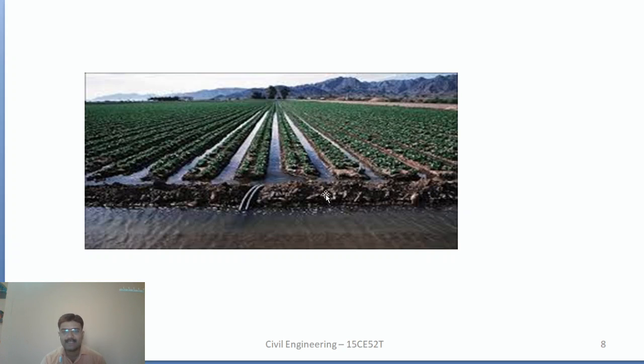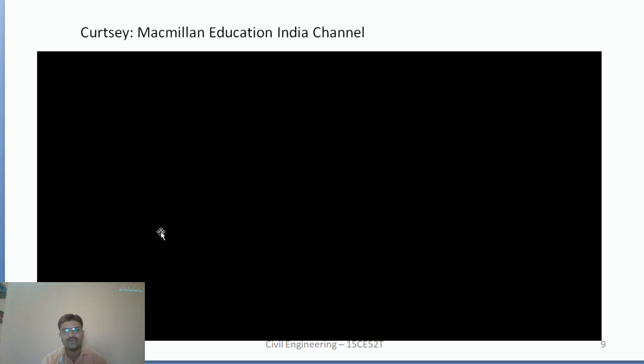Now similarly, the second row is opened, water is made to flow, and water gets inundated into the whole second row. When this whole row is completely inundated with the water, it is closed. Now consecutive rows are getting inundated by using this furrow irrigation. In the next slide, I'll be showing you a short video of how the concept of furrow irrigation takes place.